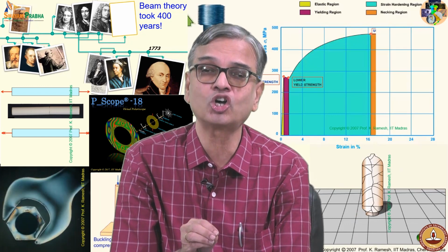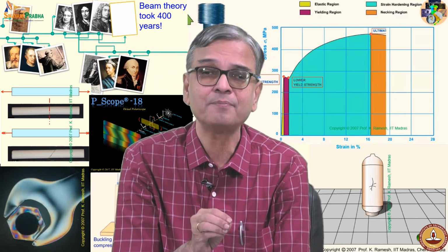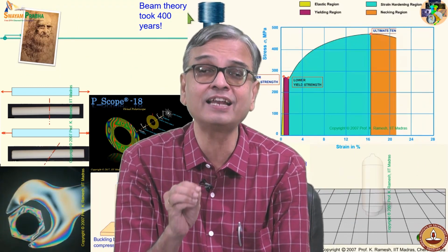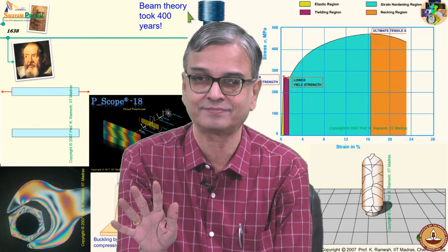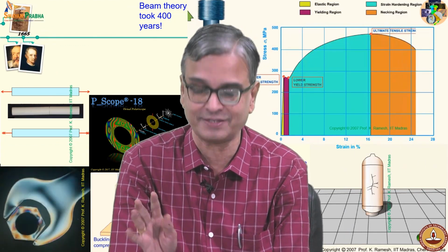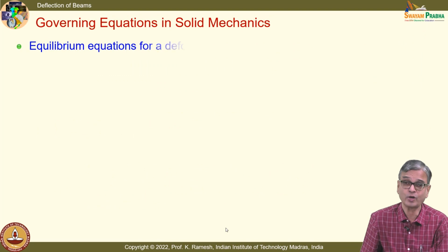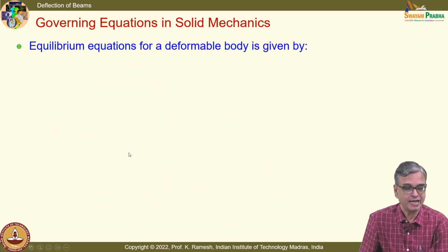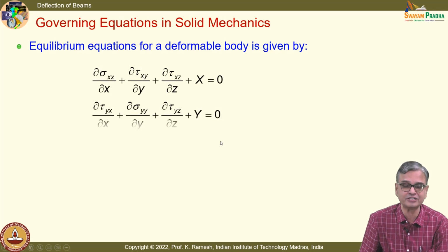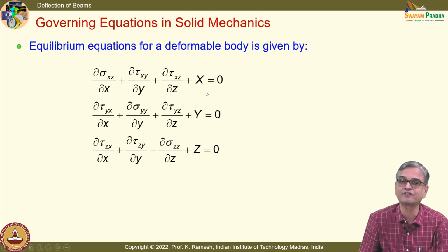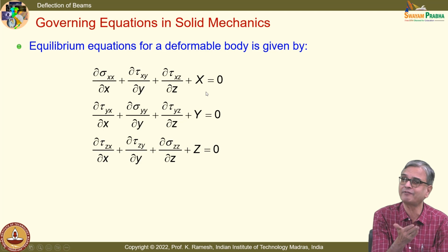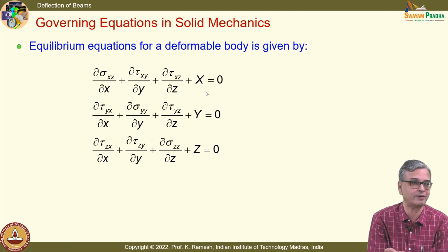Here I am going to solve and demand that my differential equation is at least solved approximately. You are not demanding mathematical accuracy. Okay. So you have a formulation. And in the case of solid mechanics, the governing differential equation is essentially the differential equations of equilibrium, which we have developed threadbare. You know how to develop it.